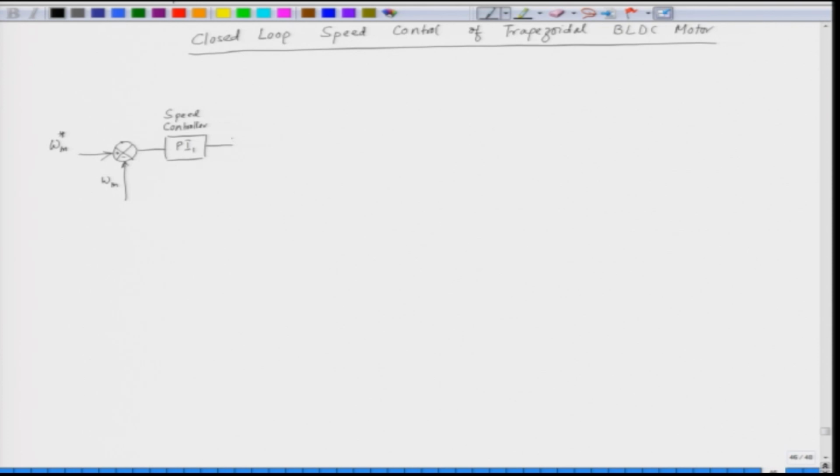and then we have a limiter, we have a current limiter here, this is a current limiter. We get the value of the current ID star. This ID star is used as a reference for controlling the inverter. The ID star is compared with the actual ID.